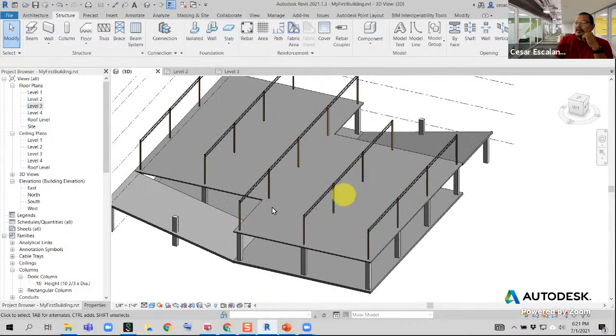All right, so in the bay between the beams, I'm going to create a system of beams. And for that, I need to load dimensional lumber. There's a family for the vertical framing in the form of columns, and there is a version of them in the horizontal one. So let's load that family.